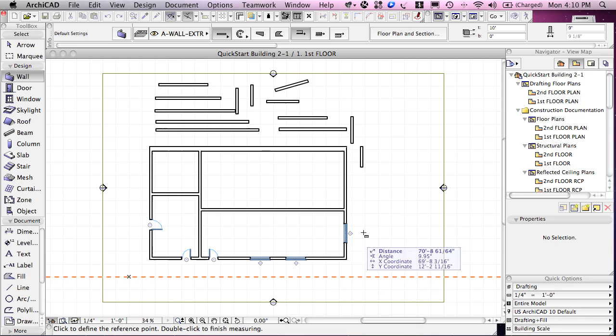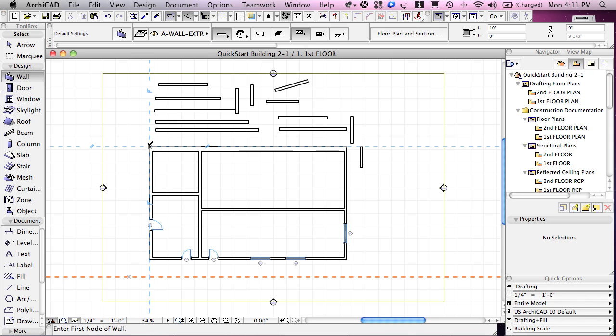Now this is called the project origin, and it actually cannot move. It's just, by definition, the beginning of all measurement references. However, sometimes we'd like to be able to measure a number of things from a different relationship, so we can use this little icon here that says Set User Origin. So when I click on that, actually I have to be out of the measure tool, so I have to hit escape. When I click on that, it allows me to, for example, click any point.